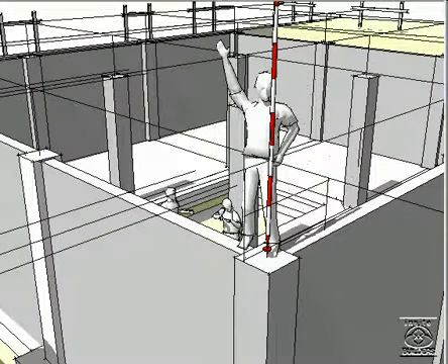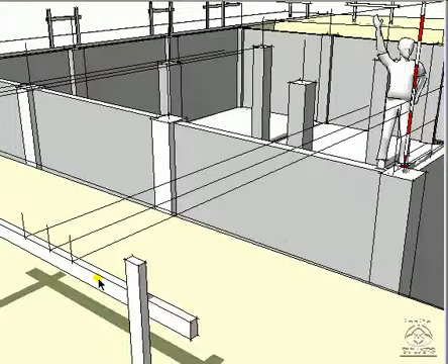So if we use the work point as a sea level reference, and the elevation of the string lines are the same, in other words they're all level, then the top of the horizontal portion of the batterboards where the string lines are tied becomes a known vertical reference. Say the batterboards and the string lines are 36 inches higher than the elevation of the reference point. Here's the reference point, string line known to be 36 inches higher. And again, all of these batterboards are set to the same elevation. In other words, they're all level.